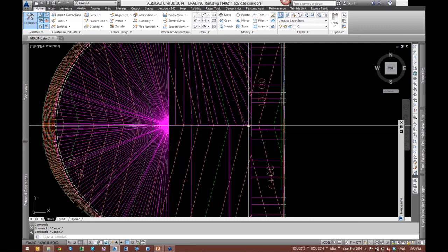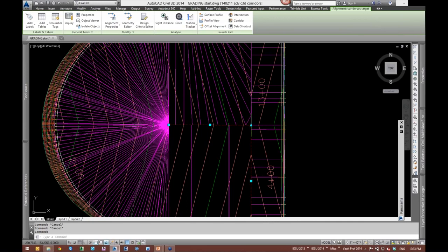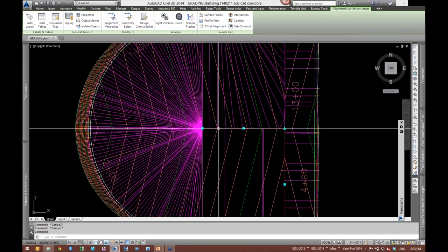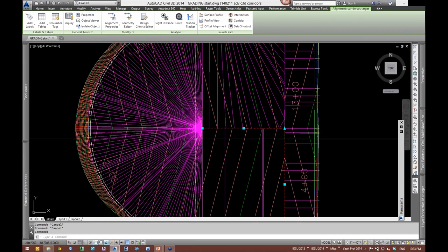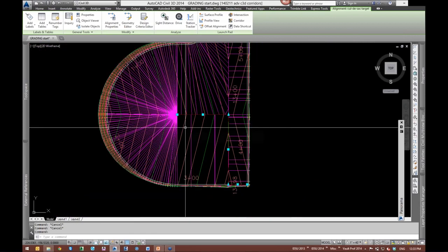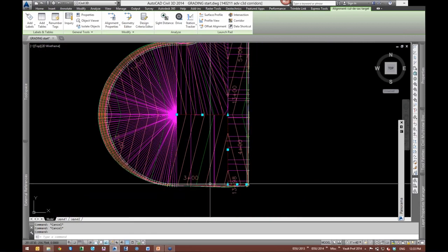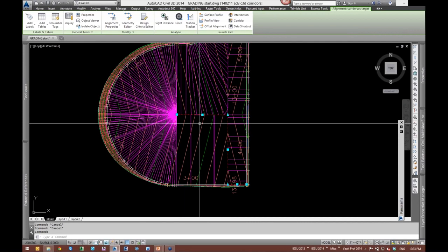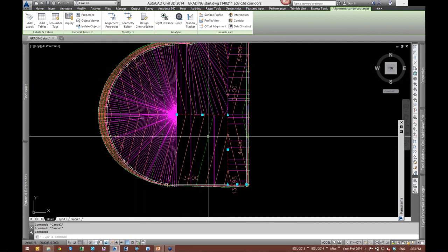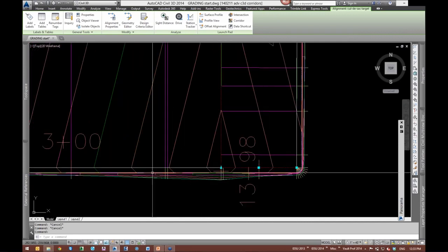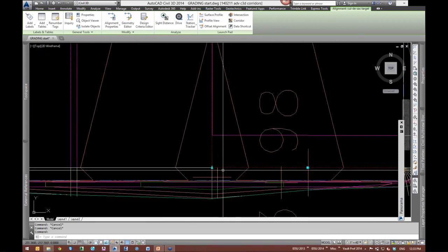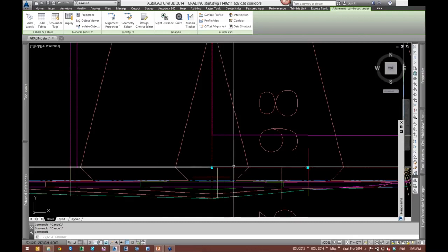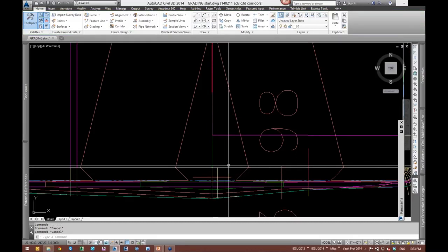Okay, so what's important here? Why do we set it up this way? Well, if we look at this alignment, this target object has to come, like I said, right to the center here to trim or to stop all of these target objects here, or these lane subassemblies. We're targeting from this angle. It's hitting that lane, and it's not overlapping the lanes on this side. And as I said, as the assembly moves right along here, I've used just another trick to have that lane squeezed down to nothing.